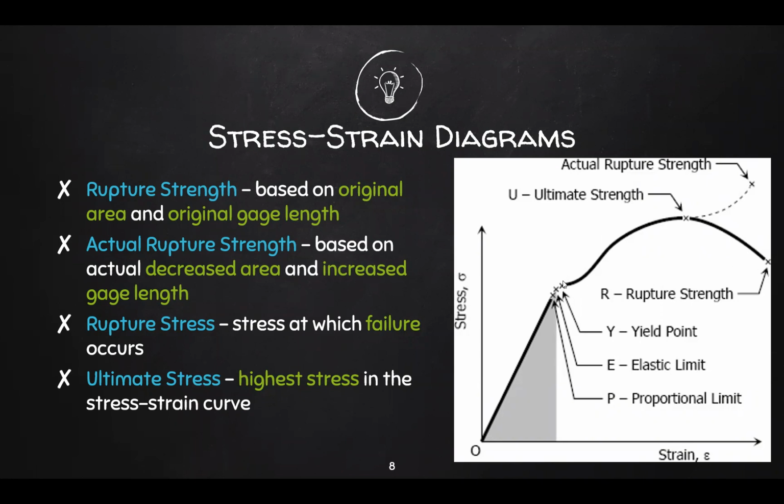So here, the point where your object will still go back to its original shape, or the point where your object starts deforming permanently. And at this point, your object starts breaking or weakening. Okay, so here it just deforms. Here it now actually breaks. And then after that, we move on to the third stage. Okay, and the third stage is what we call your necking region.